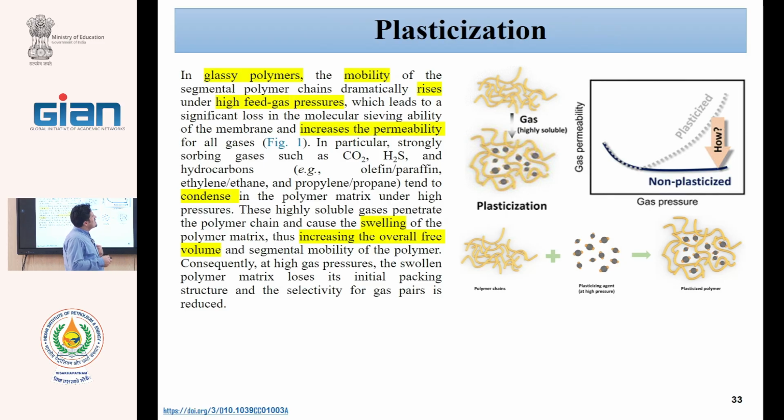One property is plasticization. Plasticization means that in the first, new membrane, we have this structure, this compaction. After 1 year, because of some impurities, some adsorption of gas to the polymer chains, the free volume between the chains is changed. Okay?